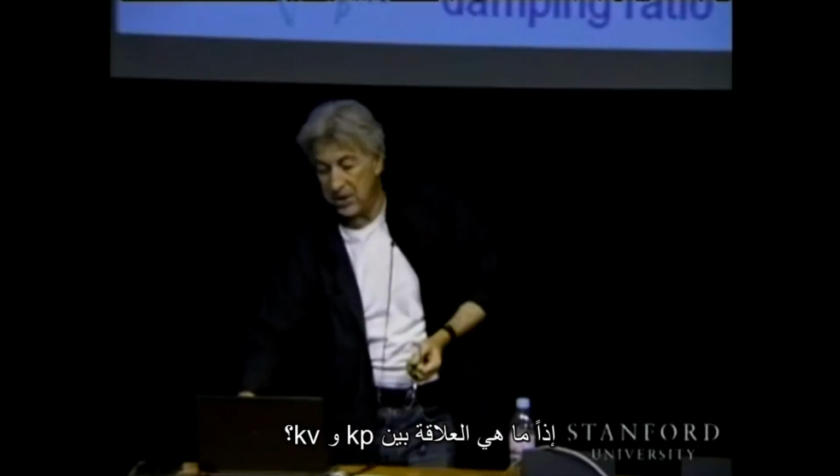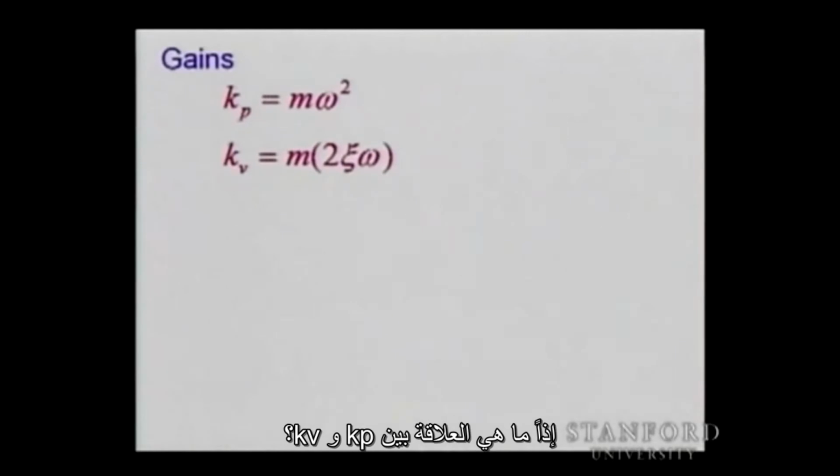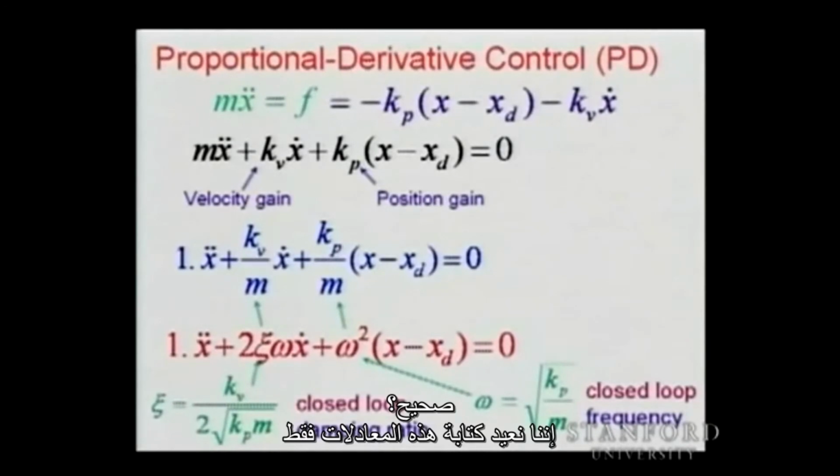So what is the relationship between KP, KV, and those performance? From those two equations, we can write KP is m omega square, and KV is m 2 zeta omega, right? Just rewriting these two equations and computing KV and KP.